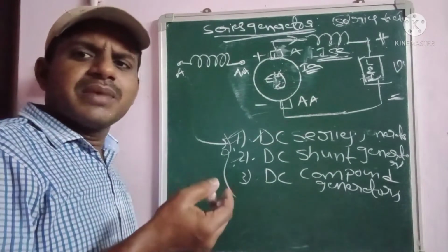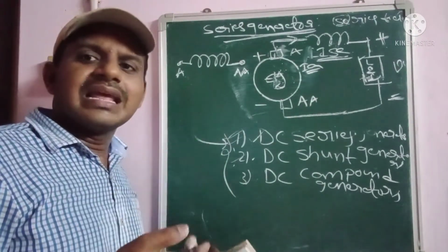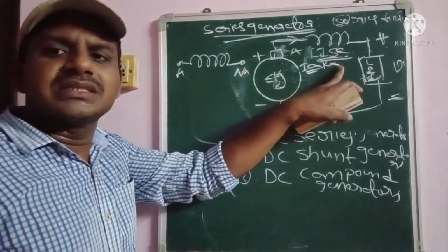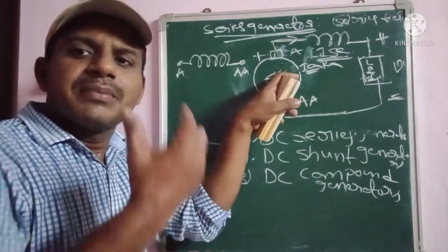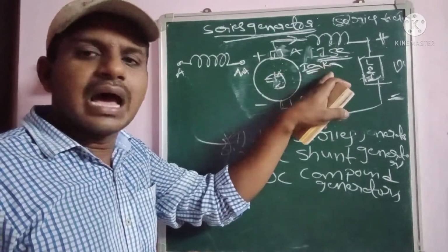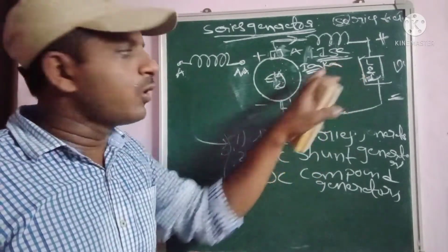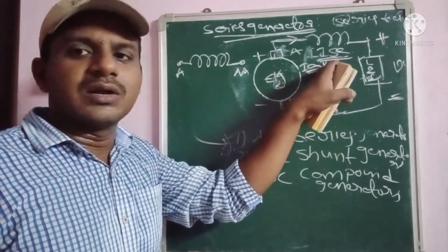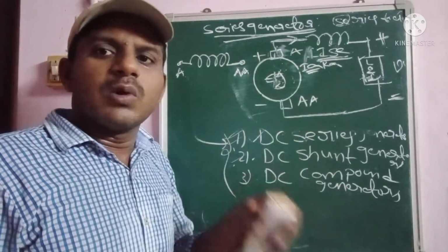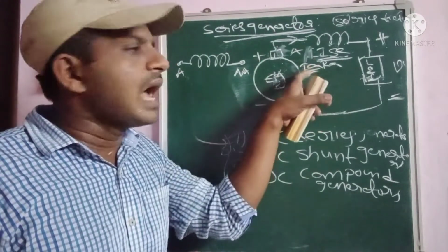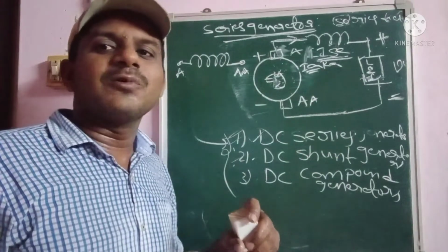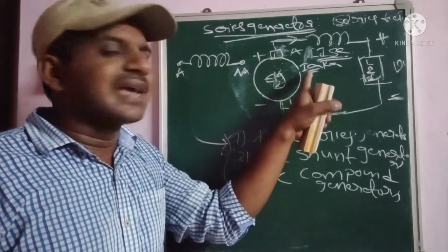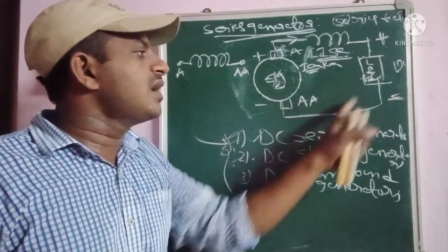As well as that, the armature winding internally has some resistance property, which is given as RA. Here A means armature, so the armature contains internally some resistance, indicated as R into A. In the armature some current IA is produced, and some resistance RA exists, so the total voltage drop in the armature is IA into RA, according to Ohm's law, V is equal to IR. So this is the whole representation.